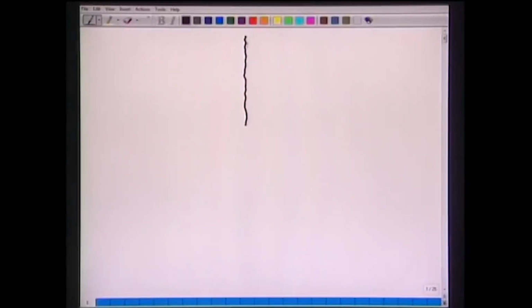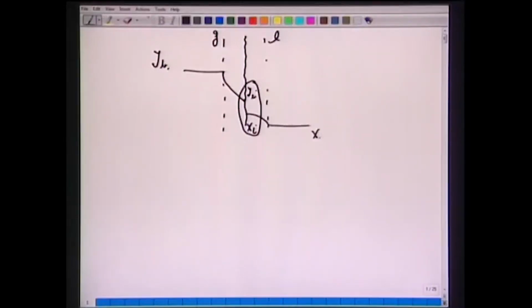mass transfer coefficients. So we have the interface, gas and the liquid, two individual film mass transfer resistances here. We have the bulk concentrations, say in the gas phase, mole fraction yB. Okay, so we can say yB here, and then it drops to the interface, say yi, then it drops from xi, where yi and xi are in equilibrium, to this bulk phase at xB.